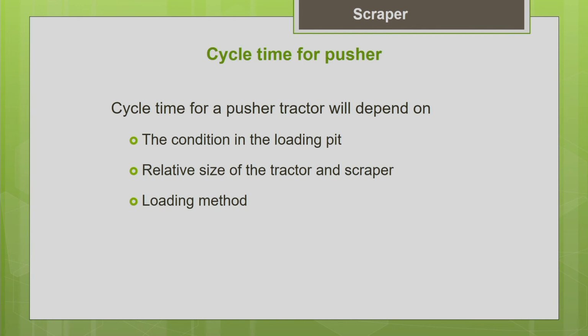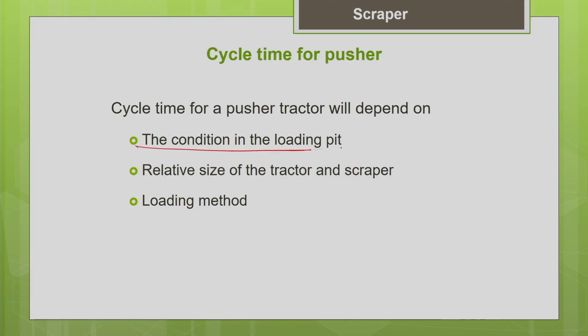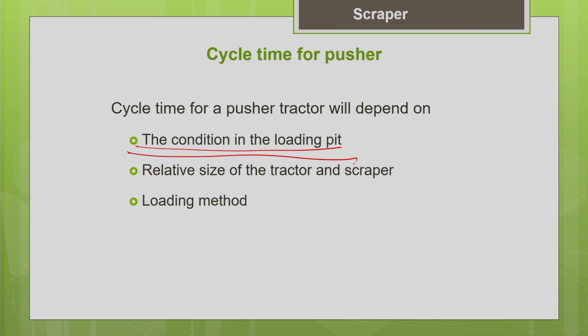So this cycle time of the pusher is variable. It depends upon various factors. Say it depends upon the condition in the loading pit. If the loading terrain is very hard consolidated clay, in that case more time is needed for the pusher to assist the scraper, and it also depends upon the congestion at your site. If the site is very congested, it will be difficult for the pusher to spot the scraper.